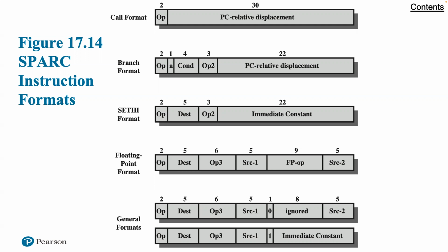The branch instruction includes a 4-bit condition field that corresponds to the 4 standard condition code bits so that any combination of conditions can be tested. The 22-bit PC relative address is extended with 2 zero bits on the right to form a 24-bit 2's complement relative address.